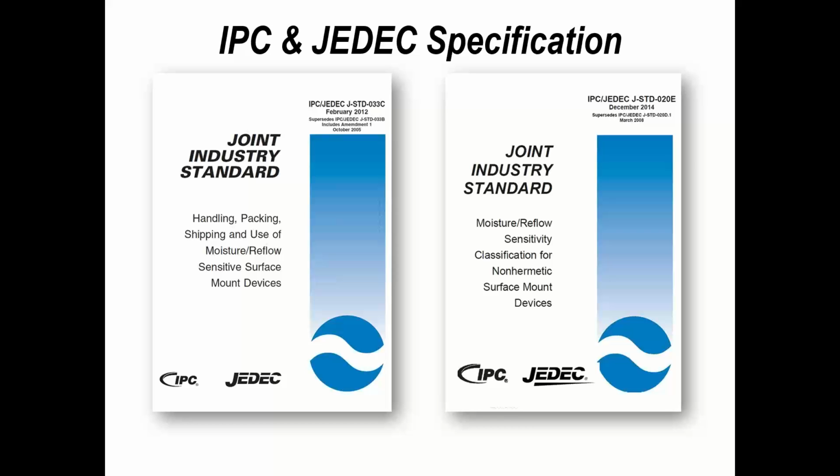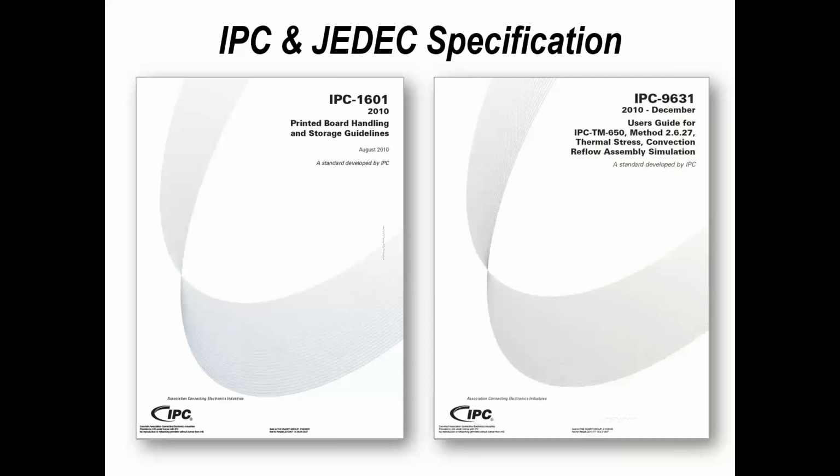So in terms of packaging, guidance, and solderability and wettability, all of this stuff is covered again within IPC and JEDEC standards. So you can review these in detail, and it gives you guidance on temperatures, time, storage conditions, etc., which we just don't have time to go into on a webinar today, but that's available. In addition, I mentioned the IPC 1601, which is printed circuit board handling and storage. And again, there are simulation tests for components that go through the reflow soldering operation. Again, that might be useful for you in the future.